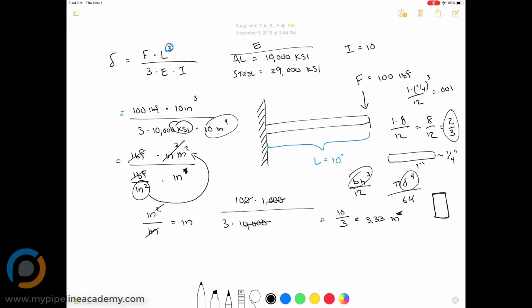I'm sure that would plastically deform it, and we're not going to get into this, but once you plastically deform a material, this equation actually is no longer valid. Material starts behaving differently beyond its plastic deformation point. This equation is only valid when the material, the object, is within its elastic range. And then beyond that, it's a whole new ball game. But we're not going to get into that.